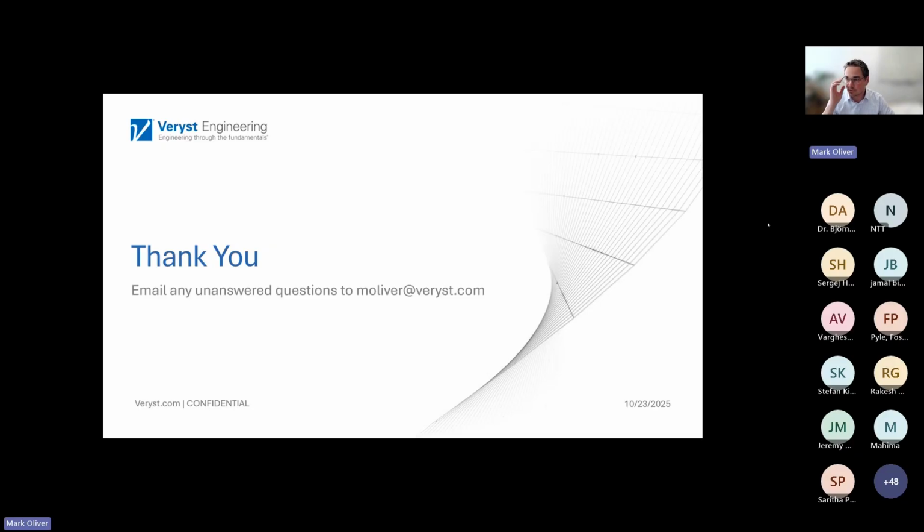All right, so the question is, for cohesive zone models, do you use node merge between the cohesive elements, or do you use tied contact? Generally, if you're using cohesive elements in Abaqus, a tie constraint is adequate. And if you can match the mesh, great. If not, that's generally not a problem.